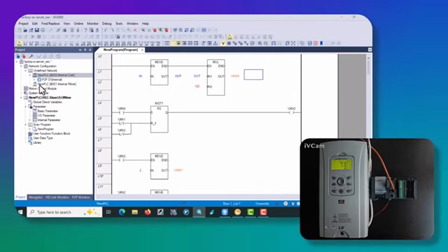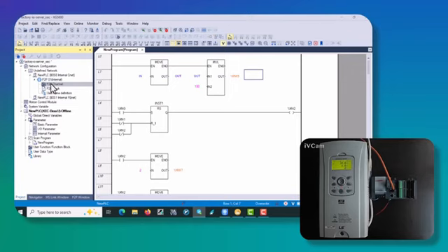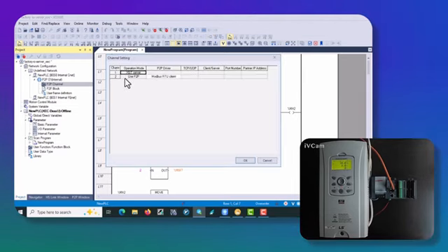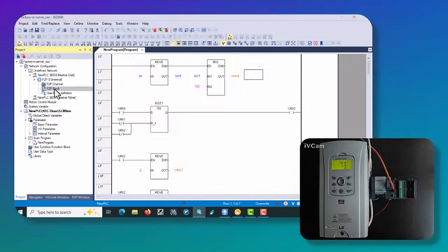When I set it to use P2P, a page appears with several options for me. Alright, in the P2P channel, since I selected channel 2, I specify under which protocol I'm supposed to connect to this device. The RS485 network, under which protocol? I select Modbus RTU client because I'm going to use the Modbus RTU protocol over the RS485 network to send data to the LS inverter. So I select Modbus RTU and click OK in the P2P block.